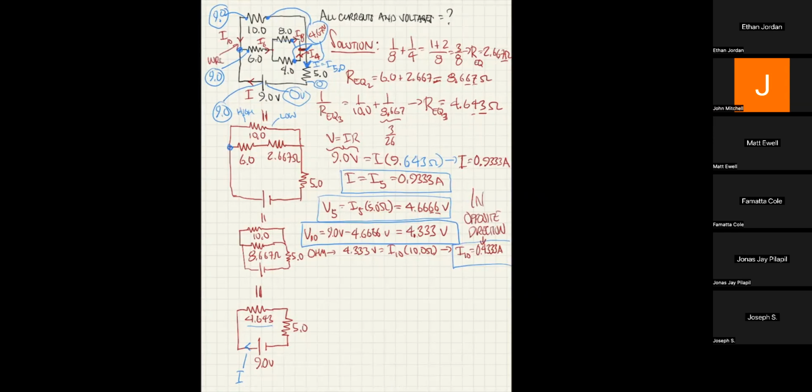So this is wrong. Okay, so that's all that happened with this one. When we do Kirchhoff's laws, you'll literally have a chance to solve for it, and it'll give you a negative. In this case, you had to look at it and say, oh, well, I see I went from a higher voltage to a lower voltage by going through the resistor from left to right. And we know that resistors are always decreases in voltage as long as you're going in the direction of the current. So I10 should technically be called like a negative there. I could put it up here if I wanted to. I would do it in blue just to show. I just want you to know I did not calculate that. I had to determine that.